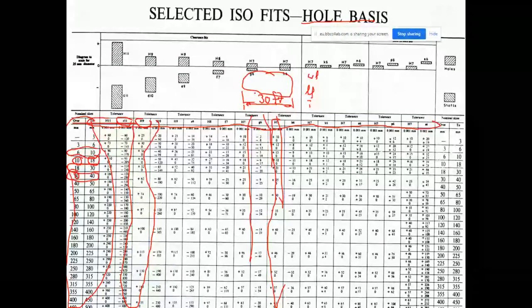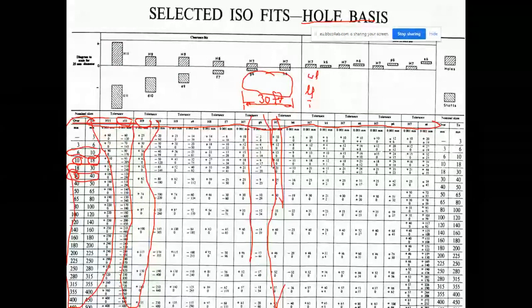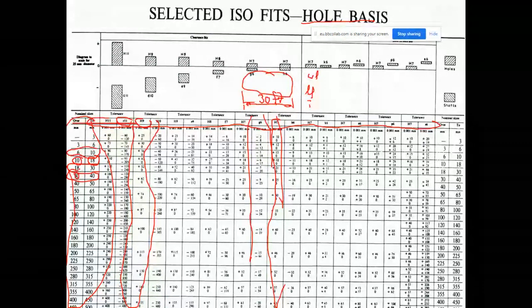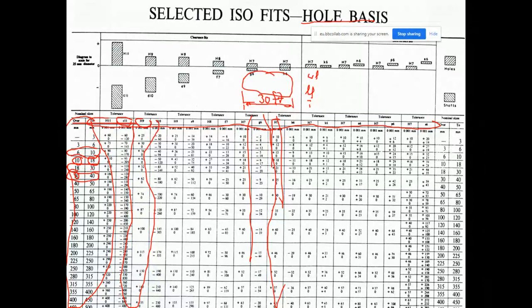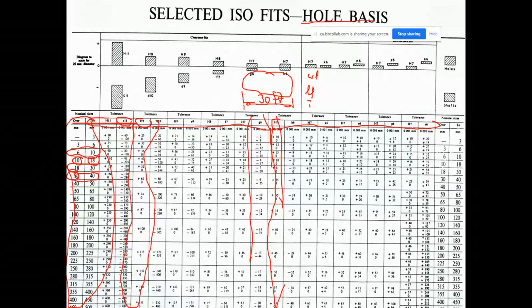For this dimension, the correct range is this one, not the next. Be careful. The first number of the ranges is not included in the range. The second number is included. Since our nominal value is equal to 30, this is the correct range.